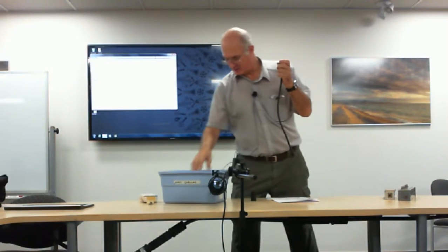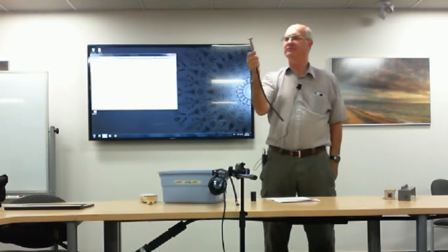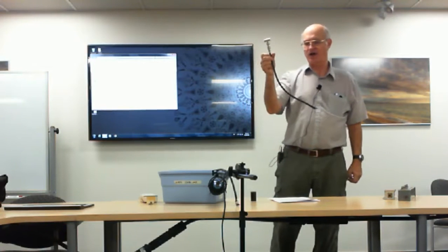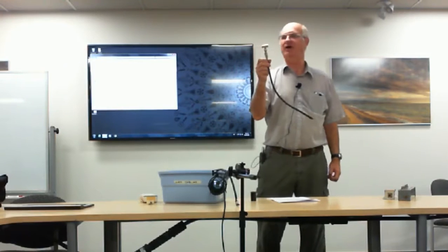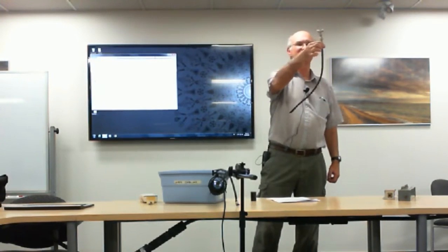And you can put this in a T, say. Do I have my piece here I need? Yeah, here we go. These are a couple I made. Just place it in line with your receiver transceiver, and that just hangs there. And believe it or not, just putting this little guy on a radio here in town, I eliminated a pager 4 miles away from causing an intermod on their receiver. Just by doing that. Isn't radio fun?